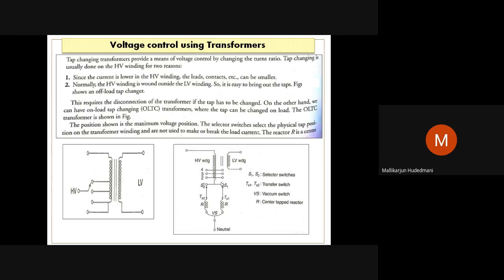Normally it is mechanized, where depending upon your required terminal voltage, a voltage which you are supposed to alter by changing the tap position, if we incorporate a microcontroller or a computer based system, an automatically motorized mechanism will keep shifting these contacts such that the required voltage is fed to the system. This way, a tap changing facility adapted to the transformer makes the system voltage controlled appropriately. By this it has really substituted the loss of voltage.